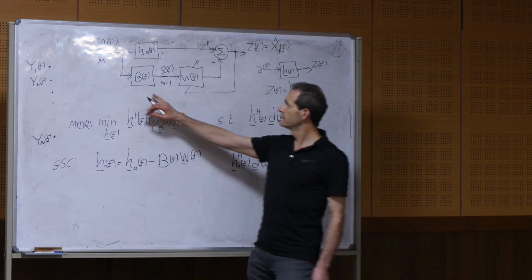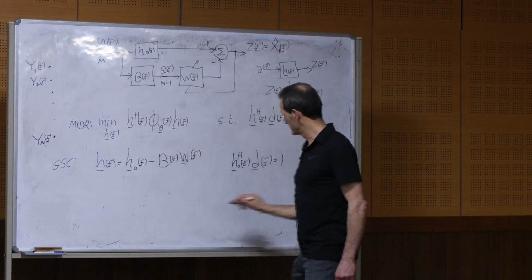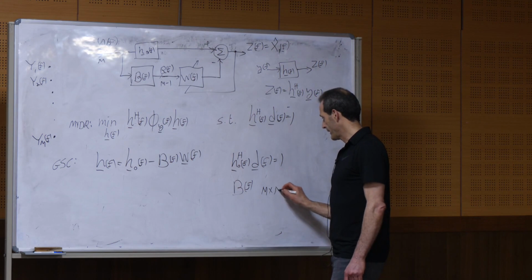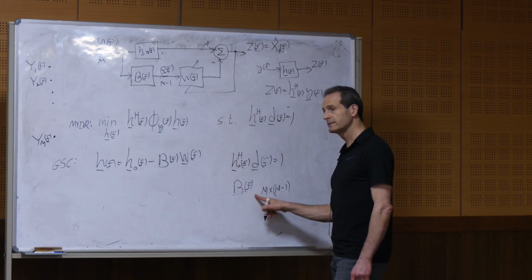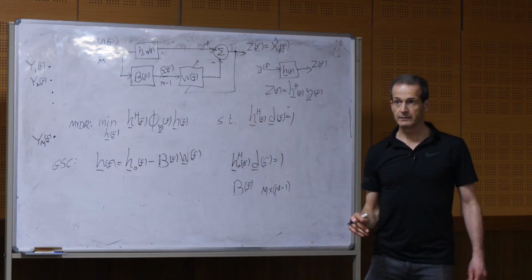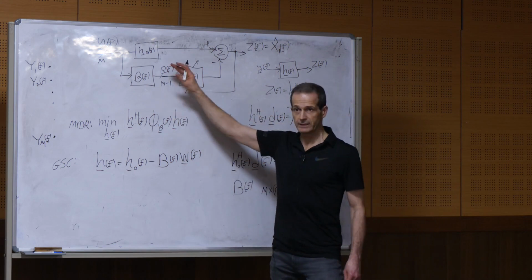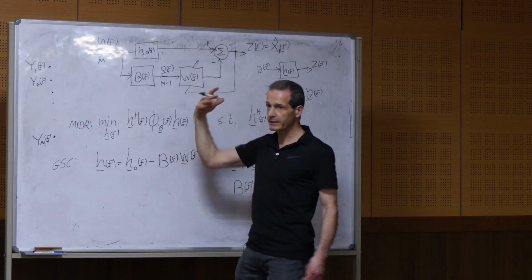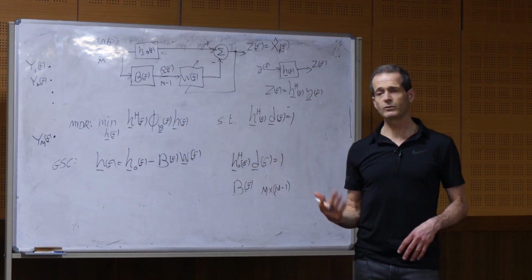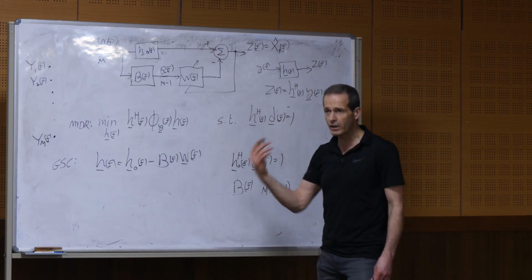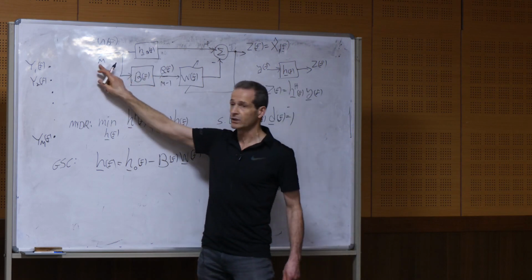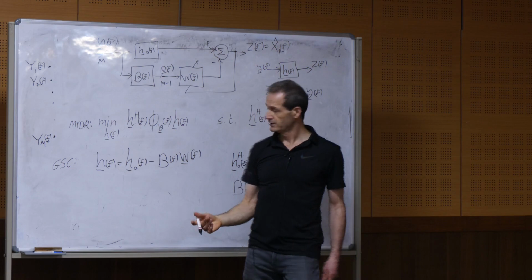The blocking matrix is a matrix of size M by M minus 1, such that we have here M minus 1 channels that don't contain the desired signal, okay? So this is the dimension. We started with M channels. Now we have M minus 1 channels. So these channels don't contain the desired signal. So this is the blocking matrix because it blocks the desired signal at the output. And the maximum channels that we can get out of M channels without the desired signal is M minus 1. So this is the blocking matrix.